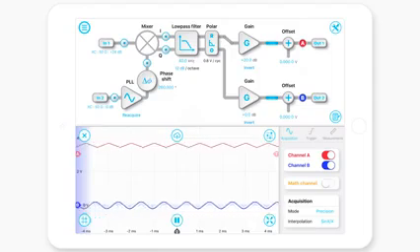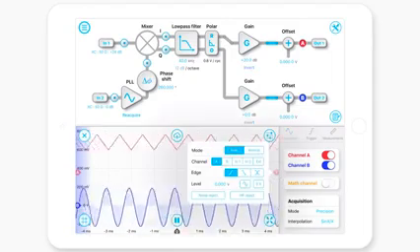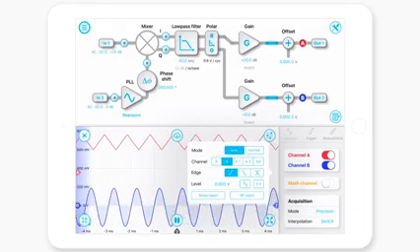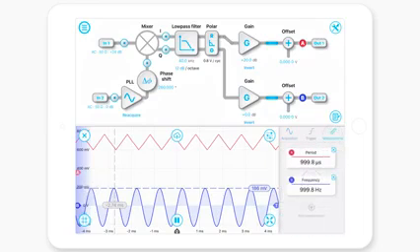Automatically adjust the vertical scale by double-tapping the oscilloscope screen, and configure the trigger settings within the corresponding menu. You can also add time and amplitude cursors to the trace, and measure important signal characteristics via the Measurements tab.